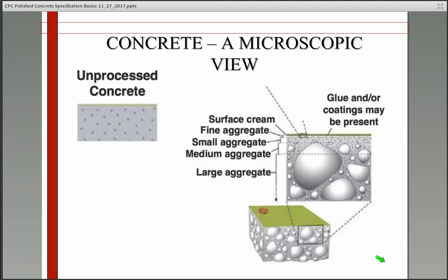Concrete, as we all kind of see it in a warehouse or in our garage in our house, has kind of almost a skin on the surface, and it looks fairly uniform. If it's been hard troweled, then it's a darker gray. But once that's removed, what we're going to see underneath it is that there are large and small aggregate and fine aggregate, which is also what you would call sand. And what happens when a grind happens is that we basically are removing this skin, and the deeper we grind, the larger the aggregate exposure typically we're going to get.